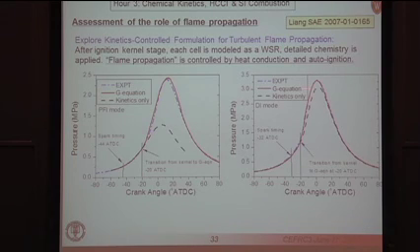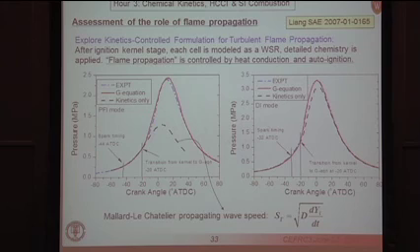I'm going to show you results with the direct injected engine next time. But the difference is not so large here because, as somebody asked about earlier, with direct injection you have fuel injection also aiding the mixing of the fuel in the air. But here this is premixed. And without a turbulent flame propagation model, you're just not able to capture the correct flame speed.